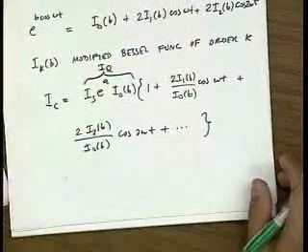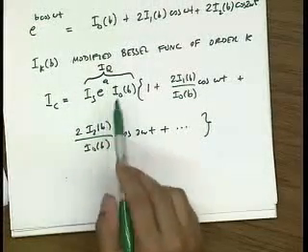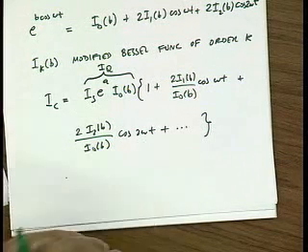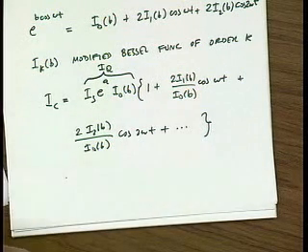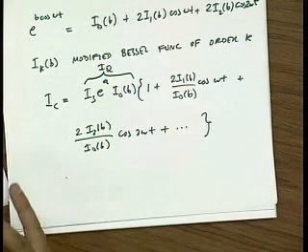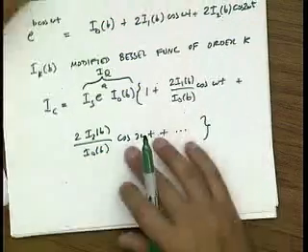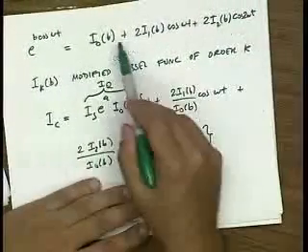The reason I factor out this term here is that very often when we design circuits, we actually have the means of holding the bias current constant. It might be like biasing through a current mirror or using emitter degeneration. But there is some means of holding the bias current roughly constant. So as I apply my large signal, this is what happens in general.